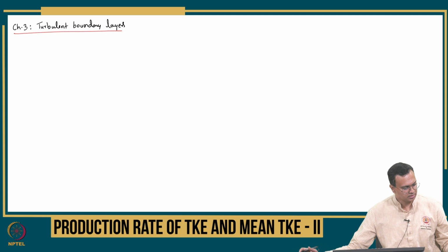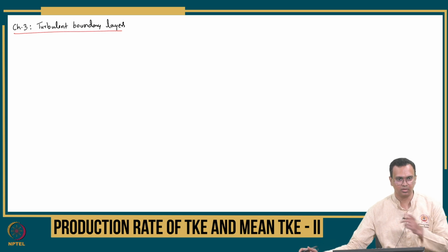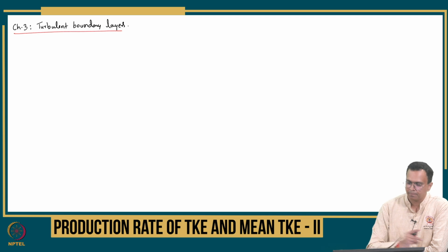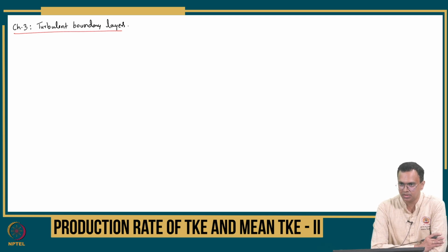all right, let's just look into a question Saket asked, right? So for the presence of turbulence, for turbulence to be there in your system, walls must be there. Okay, so walls must be there. If you have no walls, then you must have stratification. Without walls, without stratification, you cannot have turbulence. Okay, so in the absence of stratification, that is temperature gradients, you must have wall.